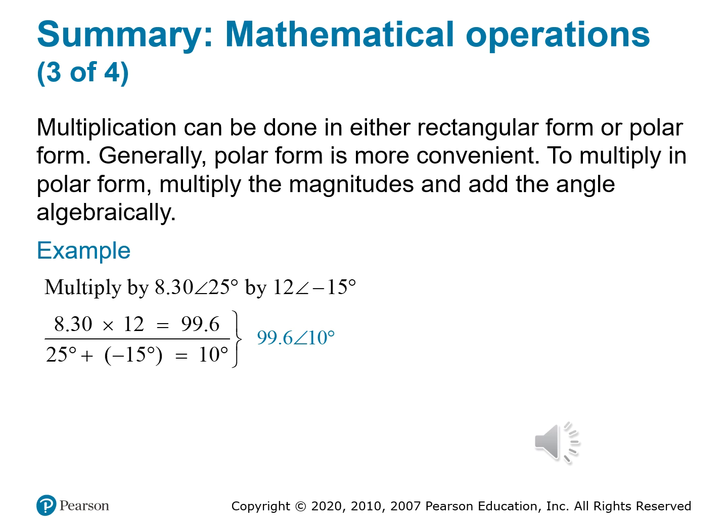Right? So with inductors, if we remember when we did this with RL circuits, the same math, same rules. The difference is just what's reacting. So L for inductors, and we did C for capacitors, right? Inductors store and delay current with that phase shift. Multiplying complex numbers in polar form helps us understand how those phase shifts interact across different stages in the circuit.